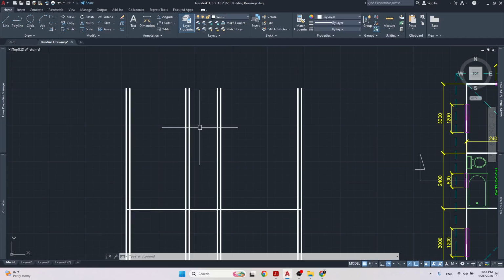They might specify the distance from the top of the floor, which is this line, to the top of the ring beam as 9 feet, 2700 millimeters. And then they might tell you the specifications for the wall plate that will go on top of the ring beam.